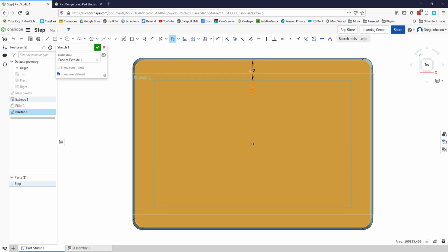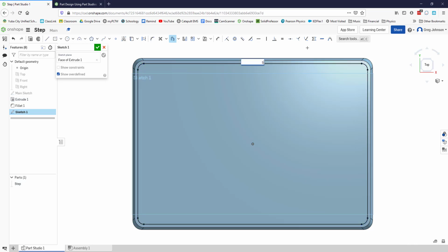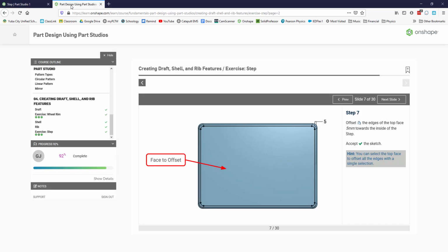This is unfixable if you get to that point. So what you want to do is get it to the point where it's just barely offset, and then click and then enter your 5. I don't know how I miraculously got 5 on the nose. That was just blind luck. But whatever you wind up getting when you let go, you've got to change it to a 5. I found that if I inset it quite a bit and then changed it to 5, it stayed a rectangle, and I was totally confused by that, and then I redid it and I noticed that. So be careful of that.